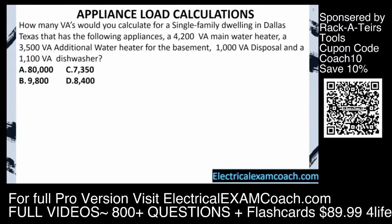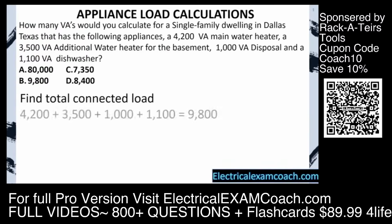How many VAs would you calculate for a single family dwelling in Dallas, Texas that has the following appliances: a 4,200 VA main water heater, a 3,500 VA additional water heater for the basement, a 1,000 VA disposal, and a 1,100 VA dishwasher? First, we're going to find our total connected load. We total it up, and it equals 9,800.